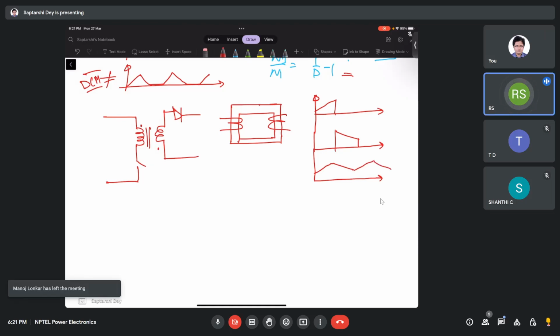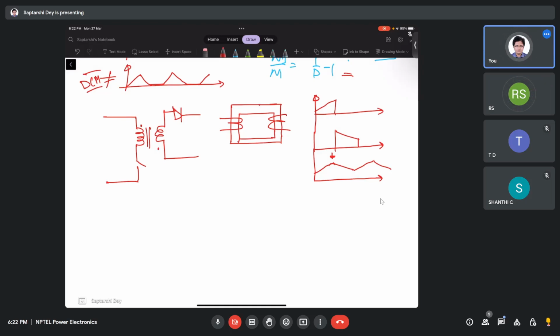That is where my doubt is. What is the question? The question is actually we are at the intersection point. The flux is increasing and again it is decreasing. Sir, at the peak of the flux value, the flux actually drops because the primary current actually drops to zero. No, see, in the secondary side we do not have any active switch.